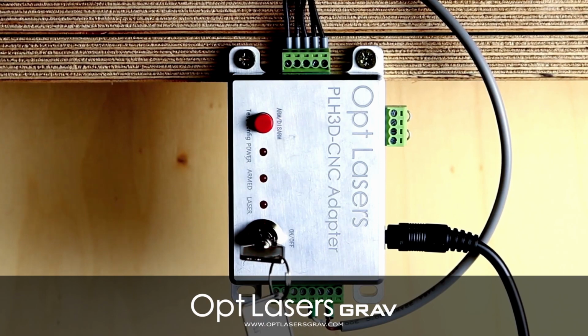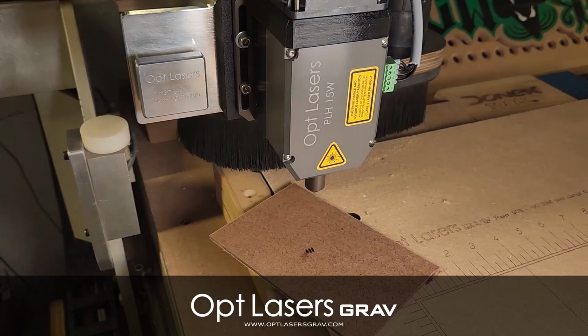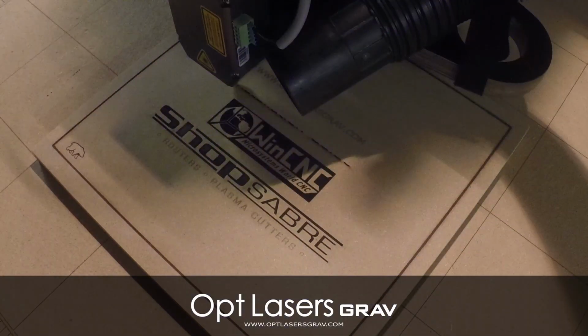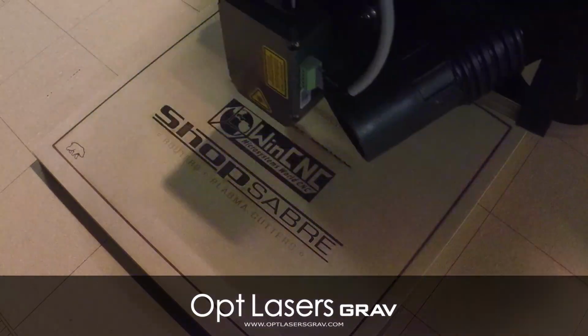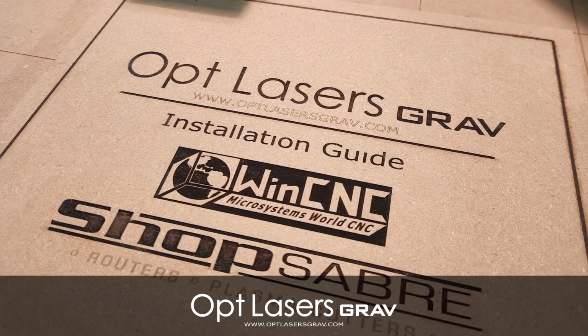We should power up the CNC adapter, and we should see if we're making good communication with the laser head. It looks like everything is working as it should. The next step is to open WinCNC and run a laser file. This concludes the installation of our laser to a ShopSabre CNC router using WinCNC control software.